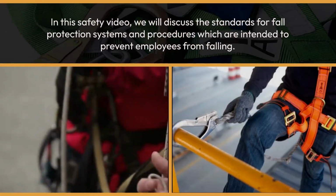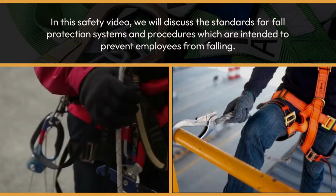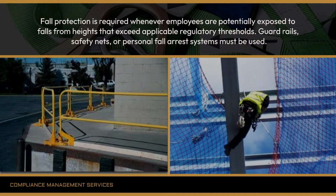In this safety video, we will discuss the standards for fall protection systems and procedures which are intended to prevent employees from falling. Fall protection is required whenever employees are potentially exposed to falls from heights that exceed applicable regulatory thresholds. Guardrails, safety nets, or personal fall arrest systems must be used.